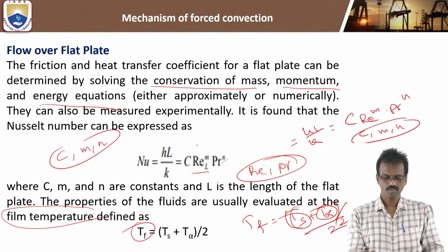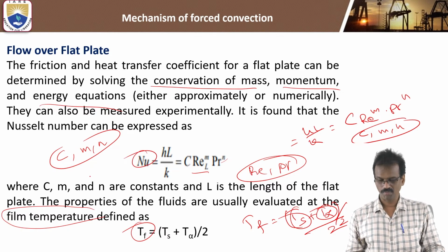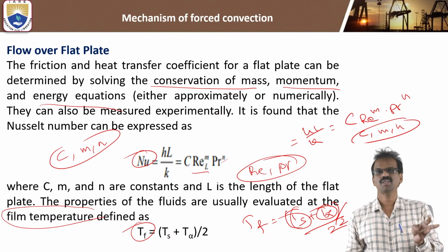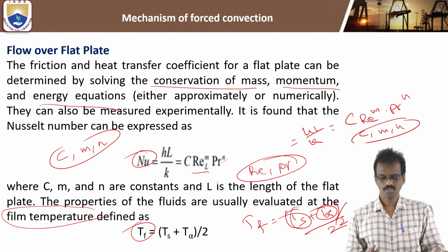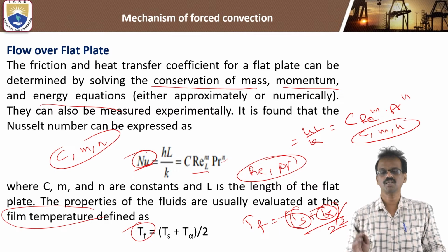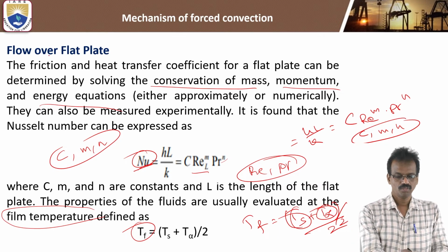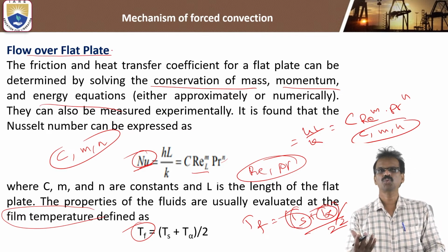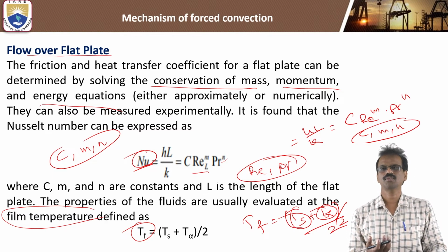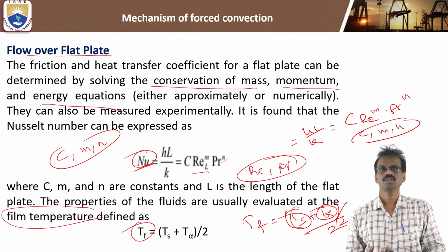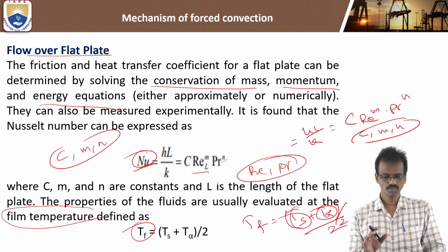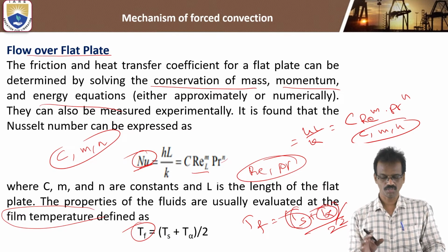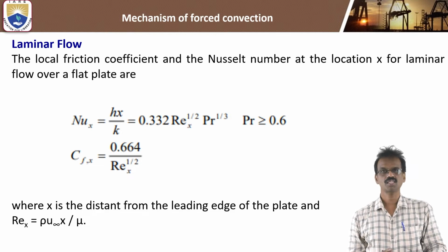So types of Nusselt formulas based upon the flow type, laminar and turbulent, because the Nusselt formula depends upon the type of flow and the geometrical structure. It means flow over a flat plate, flow through circular pipes. Okay, based upon those flows through some solid structures, the C, m and n values will change. You'll see some standard formulas.